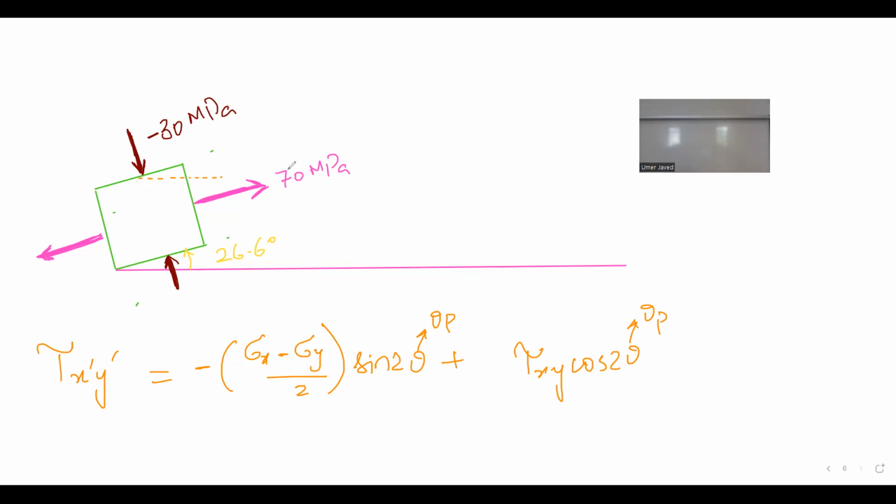We actually can. You know why? Because even if, for example, I subject this to a very simple normal stress, both of us know that if I am putting 2 megapascal of normal stress, right, then what exact value will I have? I will have stress x equal to 2 megapascal, correct? Stress y equal to 0. What about shear stress? Right now, just imagine I'm talking about exactly this square cube, when I'm putting a load.